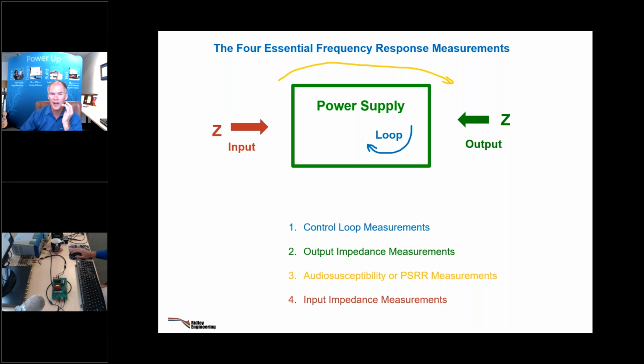So when people strive for low input impedance or high input impedance, very often they're defeating the point of the power system. And Middlebrook's talk about the interaction on input impedance is a very specific case that doesn't include the input filter, and you never measure that. So that's why that measurement is like, yeah, you can measure it if you like. I suggest you actually predict it and then put the demarcations on the power system where they belong. But that would be the topic of a more advanced separate webinar. Maybe we'll do that when we stabilize that filter for whoever asked that question.